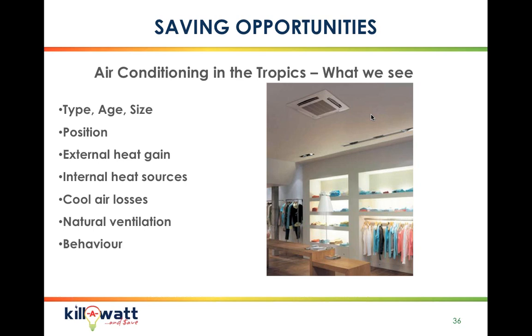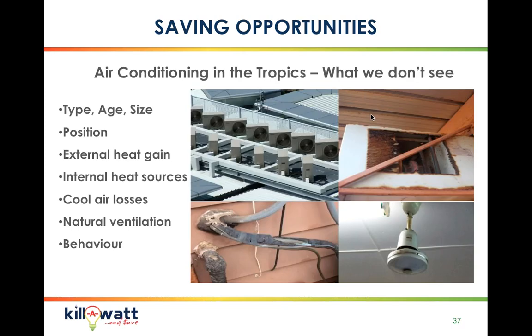Natural ventilation may not always be available, especially in the wet season. However, if you can hold off turning the air conditioning on for at least an hour or a couple of hours in the morning just by having nice ventilation coming through, that's certainly going to make a big difference to your power bill costs. The other area is behaviour, in terms of making sure people are vigilant about closing windows and doors, and setting the temperatures to make sure it's comfortable but not necessarily very, very cold.